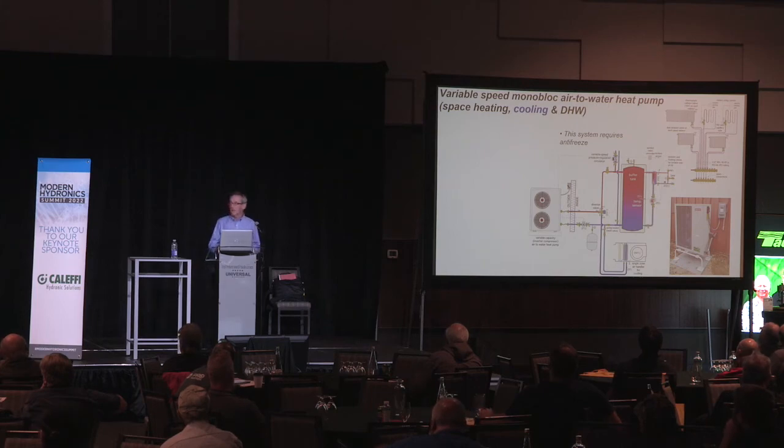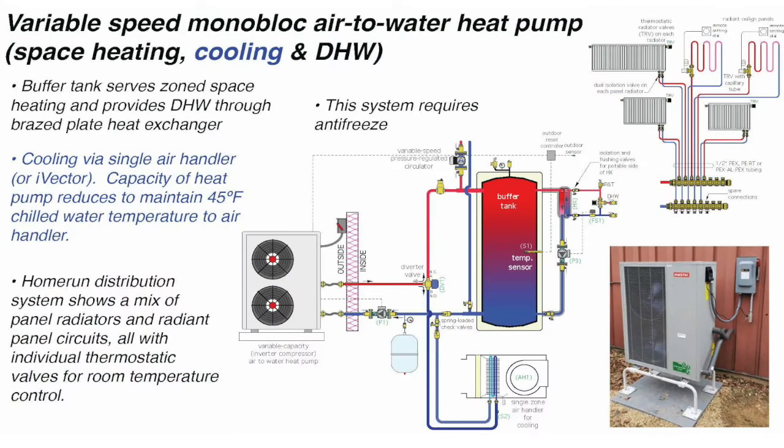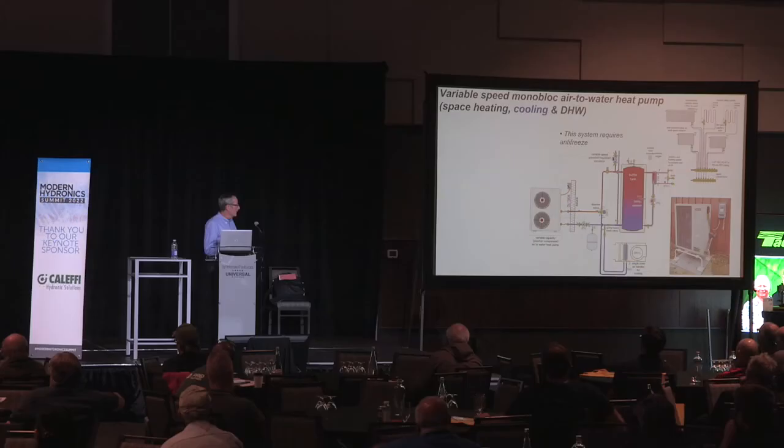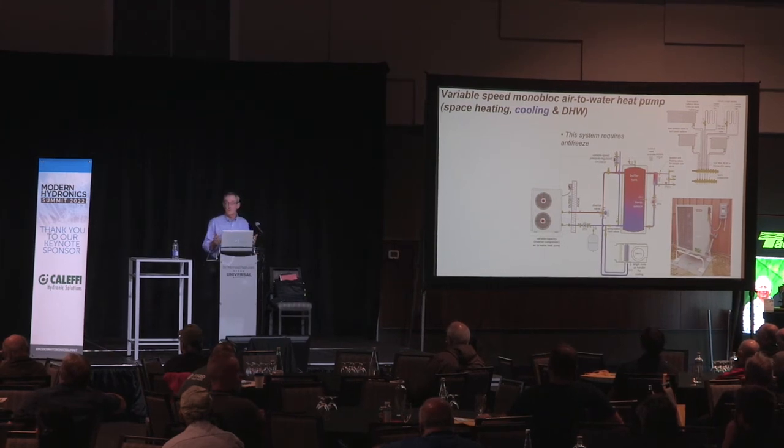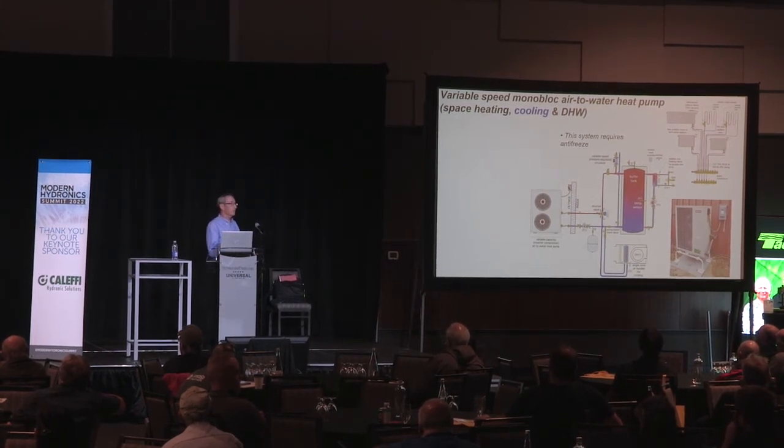and talk about response time. You'll have water temperature almost at steady state in about 5 seconds. That is definitely faster than a gas-fired tankless water heater can bring you up to a set point temperature from a cold start. And if necessary, depending on the temperature in the buffer tank, you could run that to a booster if you want to. If your heat pump is maintaining that buffer tank warm enough to satisfy your domestic hot water load requirement, you wouldn't need the backup.